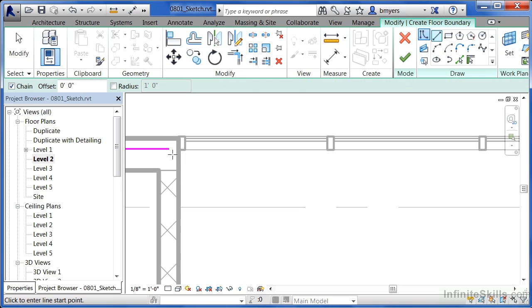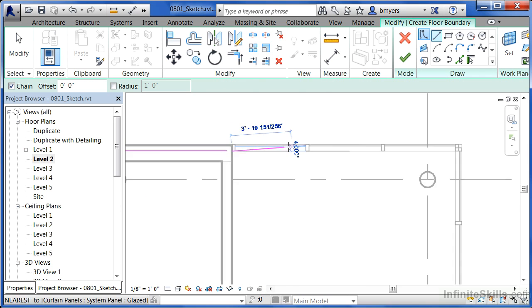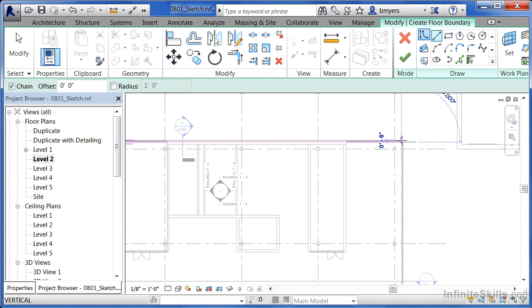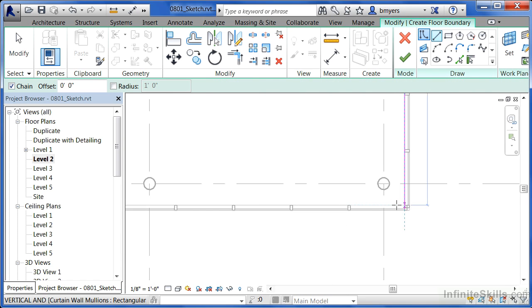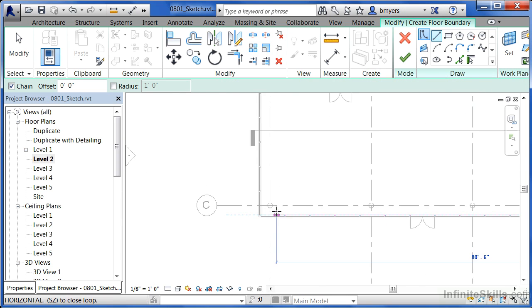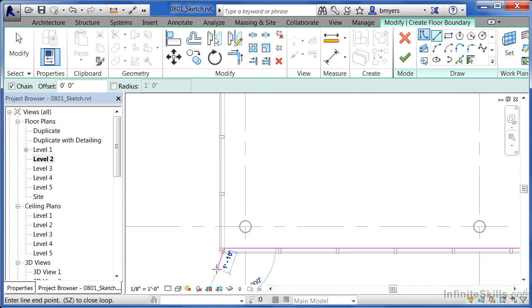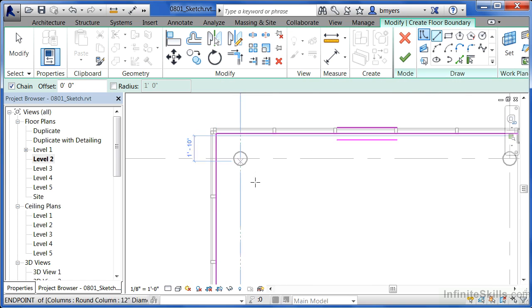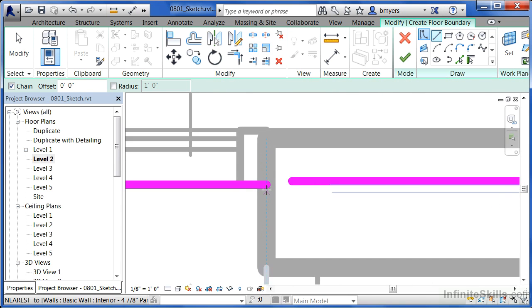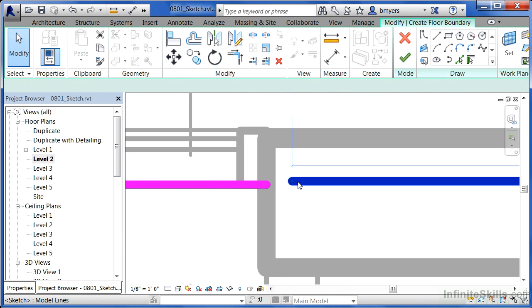Once again, pick the Line tool. We're going to start there. And now we're basically just going to play connect the dots, zooming in and zooming out by using the wheel on the mouse to draw our walls all the way around the perimeter. Bring it back to the start. Then zoom in here and hit escape a couple times on the keyboard.